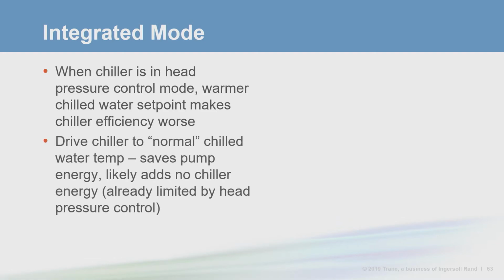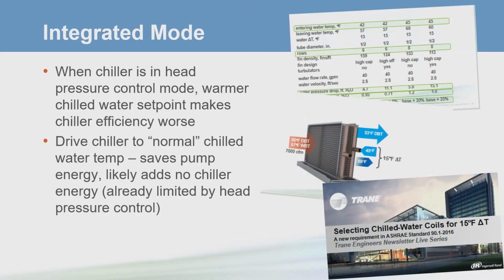It wastes no energy because it allows the chiller to perform more cooling for the same energy input. That means the coils will start to perform better and our system delta T should go up, with a higher return water temperature entering the free cooling device. As supply temperatures go down, valves close and flow goes down. At the same load, coil return temperatures stay the same or go up. Our broadcast earlier this year discussed coil performance. Please check that out if you missed it.